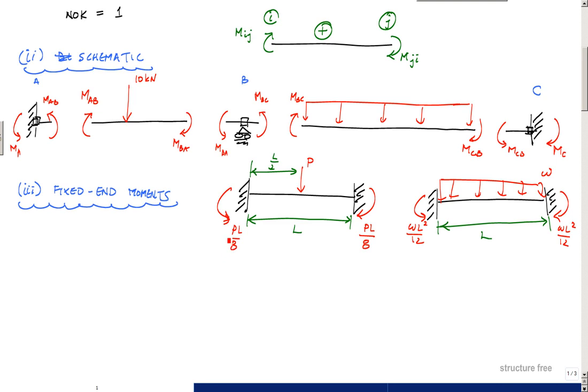And the negative only comes into play depending on how the fixed end moment relates to your beam end right here, the way you've drawn MAB, for instance. So for instance, now, if I'm looking at the fixed end moment for AB here, that suggests the fixed end moment at this location of member AB with this concentrated load. This fixed end moment goes PL over 8 in this direction. This would be counterclockwise.